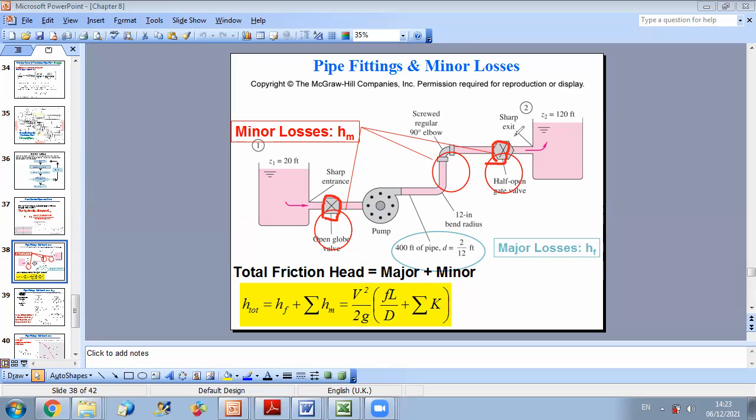This is a valve that you can control, and you can change the percentage of the flow rate with it. Each valve you put in your system will lead to losses. These losses are computed experimentally, and we have tables for them. I will give you tables telling you that if you have an open globe valve, the friction coefficient of it is K.